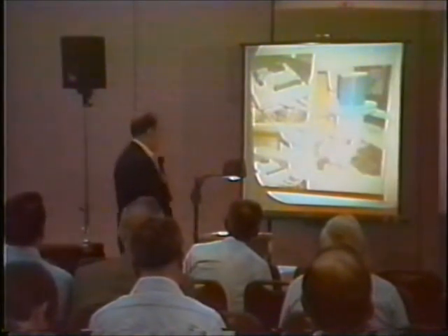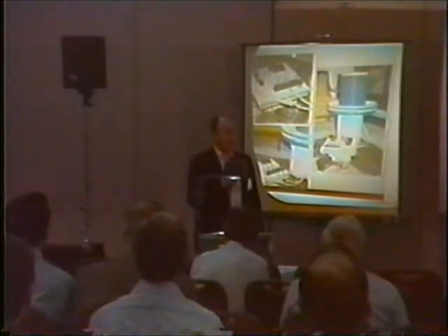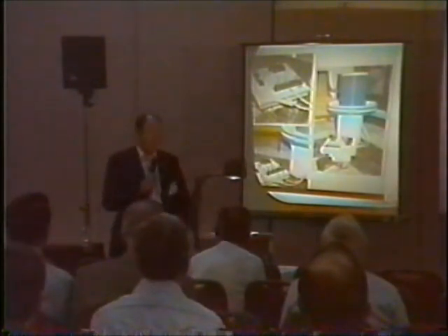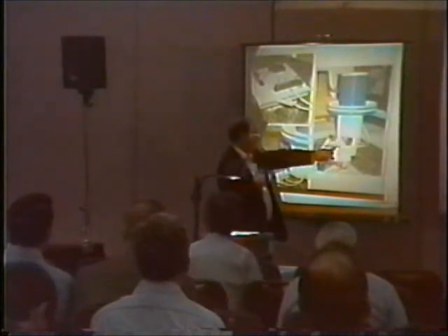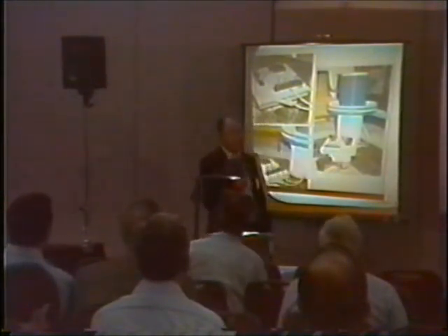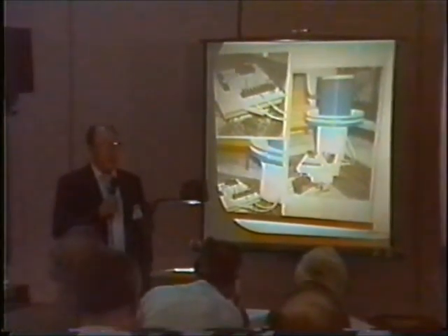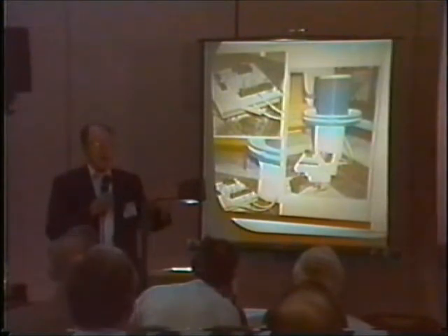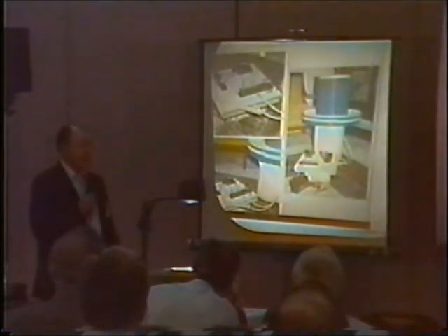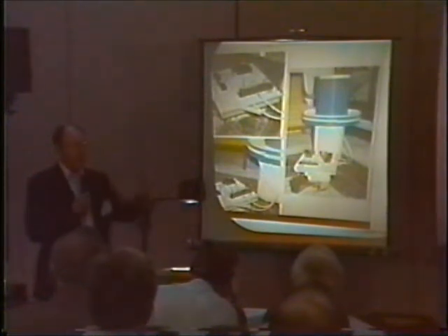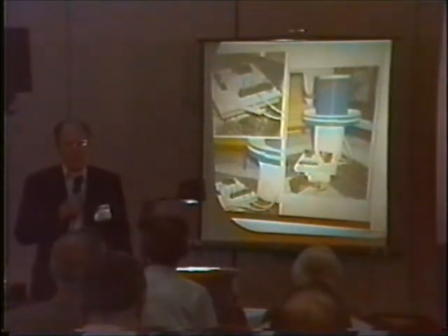And what you're looking at down below is an automobile ignition coil from a 1968 Pontiac. It's brand new, however, the coil is. And I've built a timing device onto this particular unit. It consists basically of an electrolytic capacitor, I think it's 4,700 microfarads, and it's not very large. It came from Radio Shack, and I think it was maybe about $2 and something. And there's a shunt across the two arms of the capacitor with a resistor on it. And it doesn't take a very large resistor because your basic cycles per second there are going to be